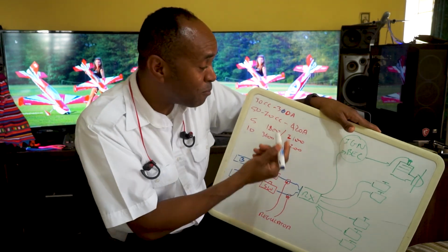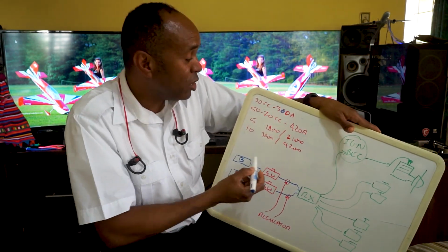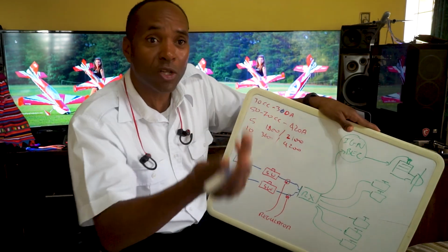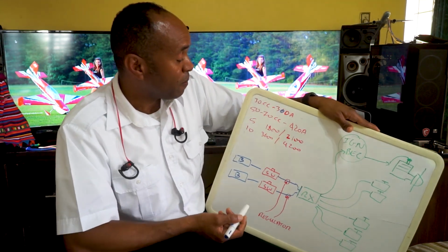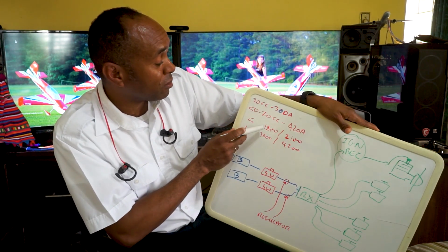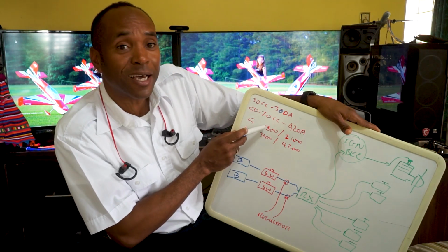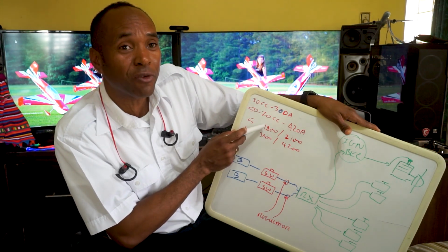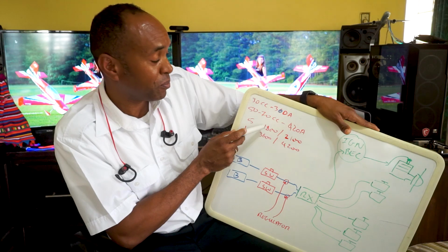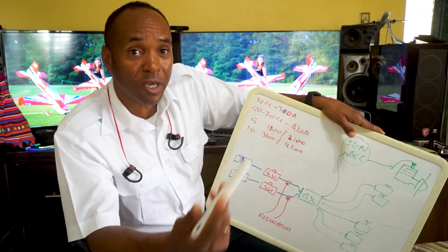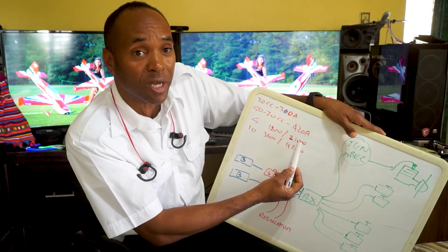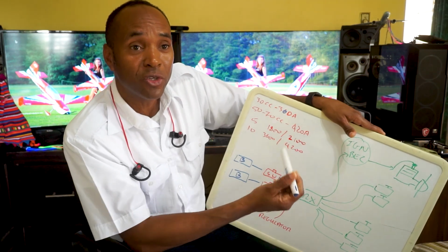This figure must represent not more than 75% of your battery capacity. So when you're going to shop for the battery for this system, you need to exceed these figures by an additional 25%. If you're a 5 flight man for a 30cc plane, you're going to need say a 2500 milliamp battery as a minimum, right? Or for a 50 to 70cc airplane, a 3000 odd milliamp battery minimum, so you can do 5 flights